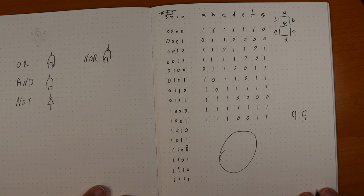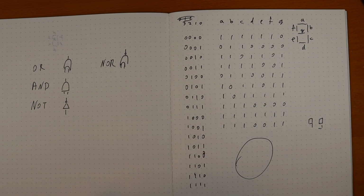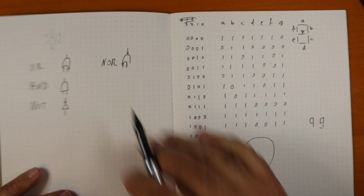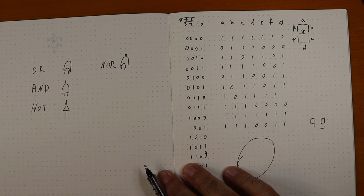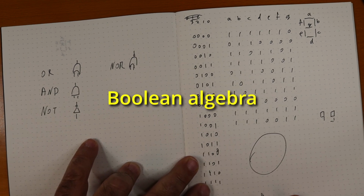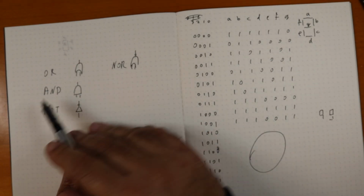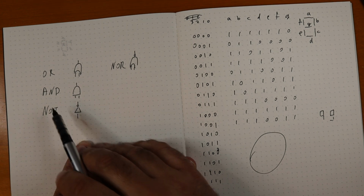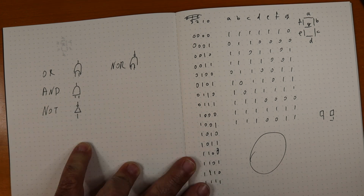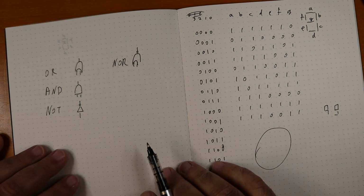Okay, so how do we convert this into this? First of all, we need a better way of denoting symbols. So we can use something called Boolean algebra. Boolean algebra looks like this. Instead of doing OR, we'll do plus. Instead of doing AND, we'll do multiplication. And instead of saying NOT, we'll do a line above the symbol. So we have Boolean algebra.